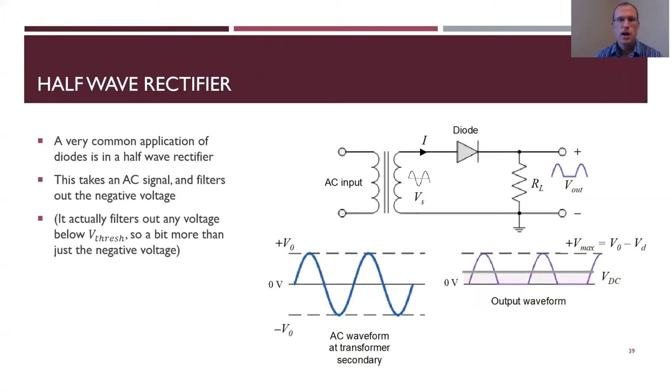So that's one application. The other application, as I said, is this rectifier. It is very useful in turning an AC source into a DC source. A lot of times you have an AC source that you want to turn into a DC source. That happens a lot, especially with things like computers. Batteries are generally DC, but you charge them by plugging something into a wall, which is AC. What's inside your little charging device is basically some of these, converting the AC source from the wall into a DC source to charge the battery.